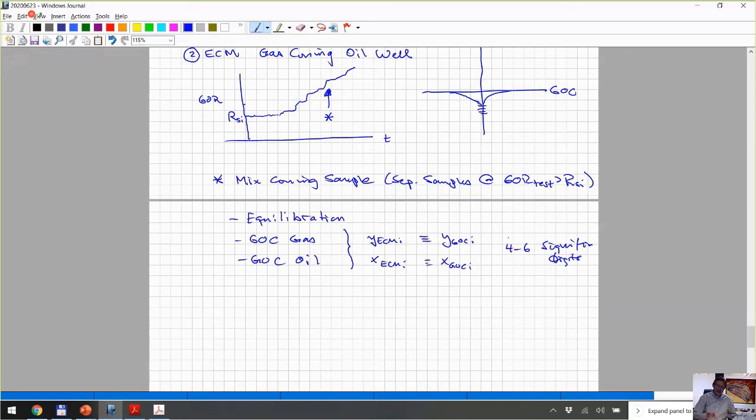The only thing here is you don't really have that much control over how much equilibrium gas and how much equilibrium oil you get, right? Because it's coning. So we have a design gas oil ratio equation in the paper that says if you go to that GOR, you'll get greater than 30% oil or something like that. There's a kind of a design sampling, but normally it's okay because you basically want to have enough gas that you'll have a gas volume that's big enough to do a CVD and CCE test on.